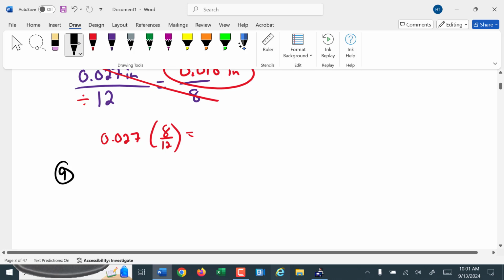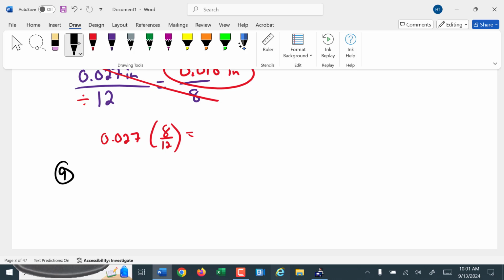So number 9, if the shaft is operated at 2,700 RPM, what is the allowable angular gap? This is in your books on that table. Page 326, yes. So if we're looking at 2,700 RPM, what is our allowable angular gap on a 10-inch flange? 0.005.